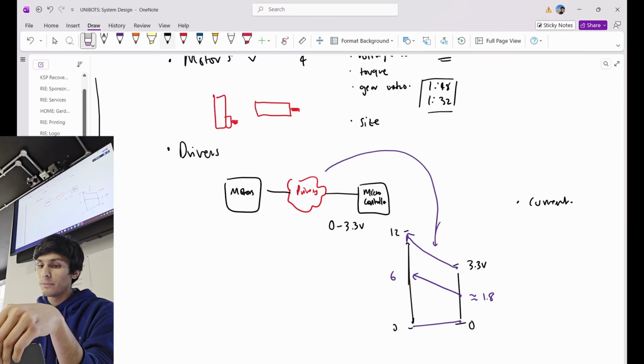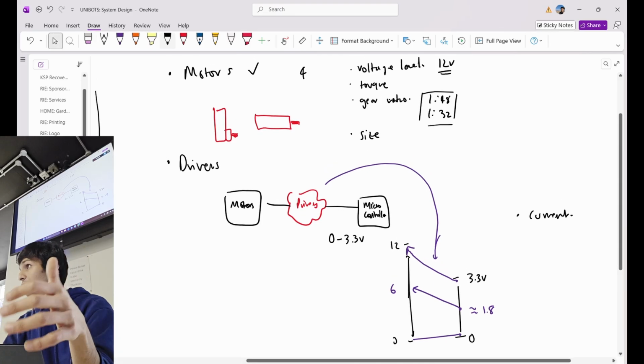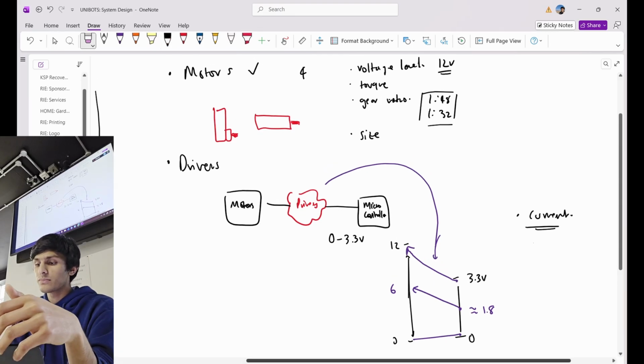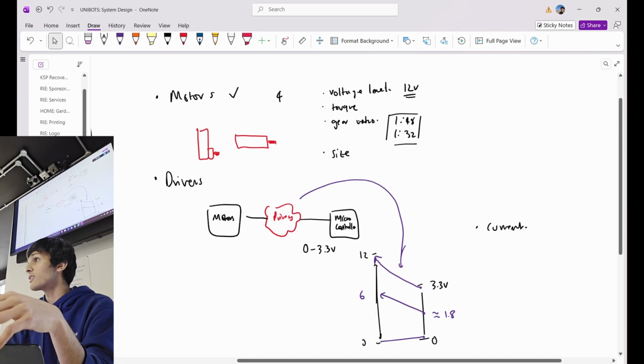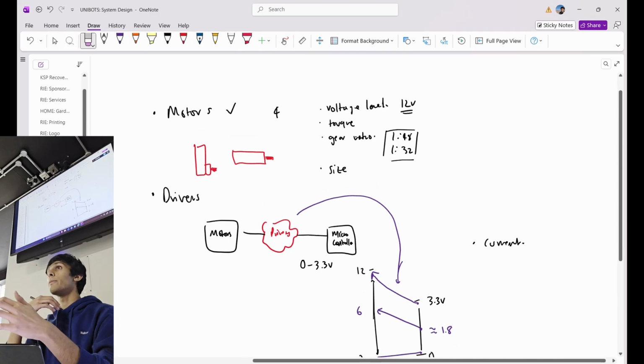Once you decide how many motors you're going to stimulate, pick a motor driver that can handle enough current, because there are some motors that are really thirsty when it comes to current. Typically, the way we are doing this is, it will burn out the motor driver.